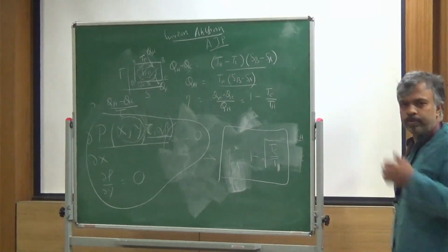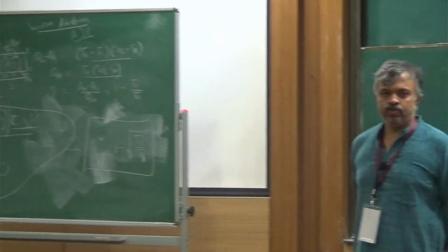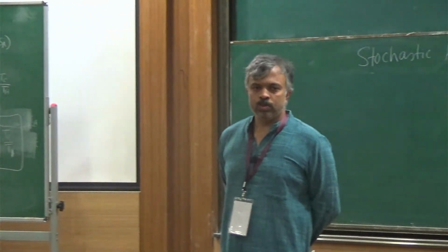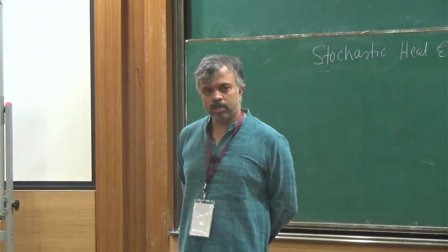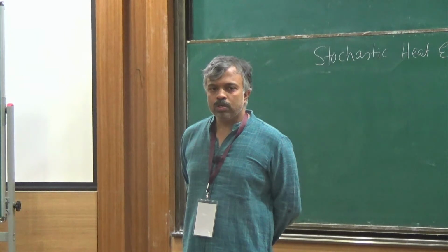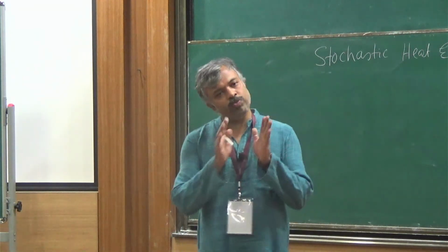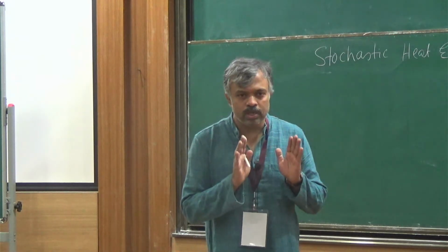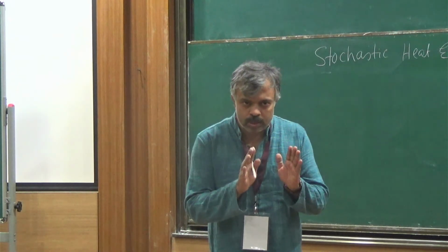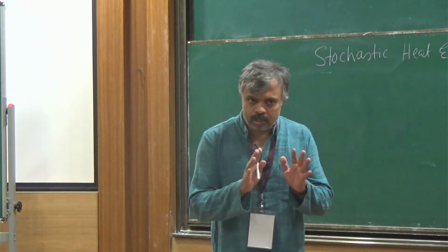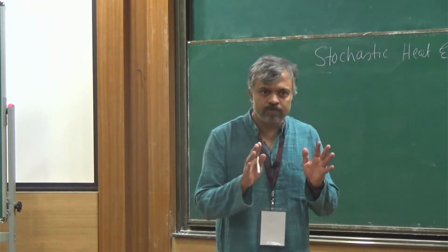So you are finally saying that the efficiency with this assumption is 1 minus Tc by Th. It is not the square root form. It is not depending on the fluid temperature. That is because of all the simplifications going in, the linearity of the cooling laws, and the endoreversibility of the engines.